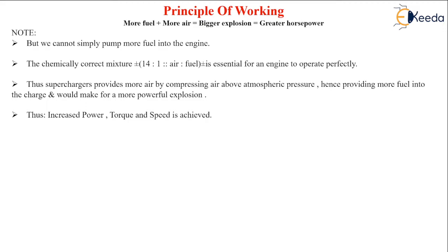Further, we see that supercharging provides more air by compressing it above atmospheric pressure. As a result, this will allow more fuel into the charge and in turn provide a more powerful explosion, thereby giving you an increased power output, torque and speed from the same engine.